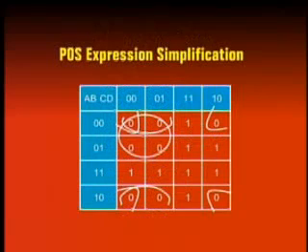An appropriate way to implement the adjacent ones detector circuit is to simplify the product of sum Boolean expression represented by the function table, and then from the simplified Boolean expression the circuit can be implemented. The circuit of course would be simpler as compared to the standard product of sum based expression.